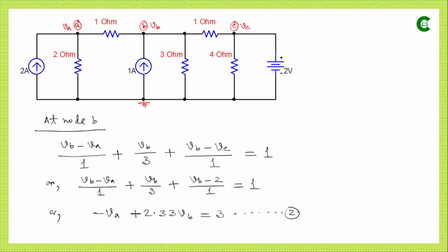Now in the circuit we have another source, which is a voltage source. For that we need to find the current flowing through this voltage source, and from there we can calculate the power delivered or absorbed by that energy source. To do that, we will analyze node C, and here we can see that we have three branches connected with node C. For these 2 branches, the current directions are not known, so we will assume that the currents are leaving.